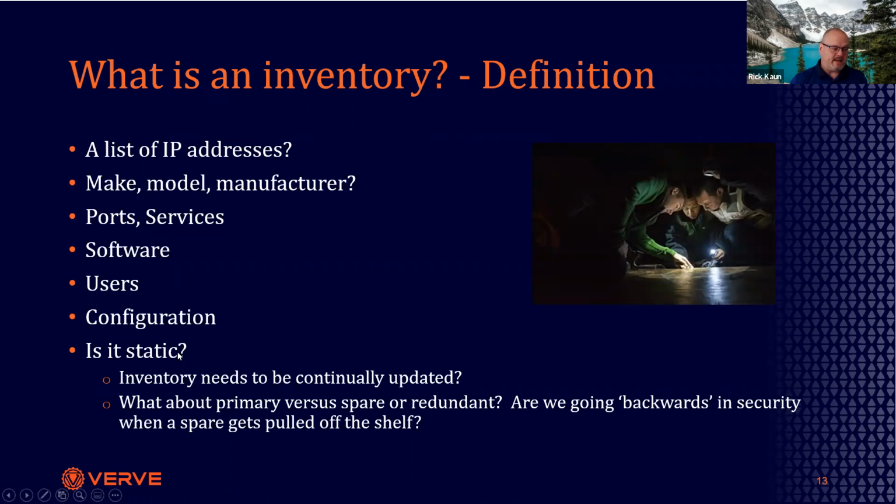And is the data static? Most people believe that OT is set and forget, but inventory does need to be continually updated. Spares off the shelf, upgrades to software, project-based adjustments. I know I came in after the alarm management team at a Matrikon project once that were troubleshooting getting the alarm management working. And they opened a whole bunch of ports in the firewall, and then nobody went back and closed them. So we did an assessment 6 months after our counterparts had been there doing alarm management and OPC connections, and realized that well-intentioned view into data to run the plant better and more efficiently unfortunately introduced a significant security risk that wasn't necessarily understood before or even aware of.